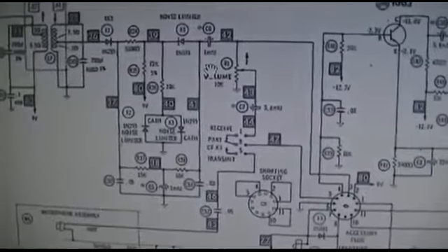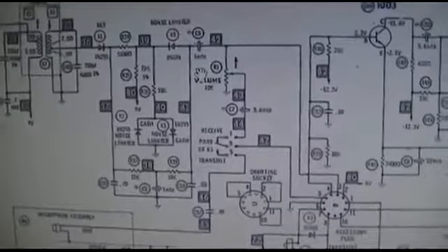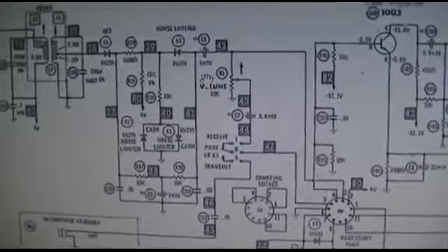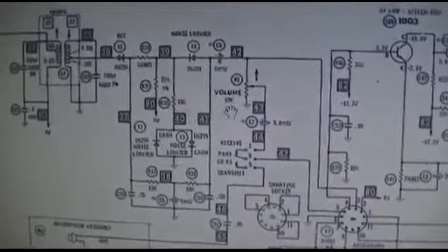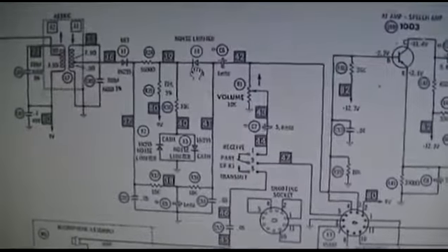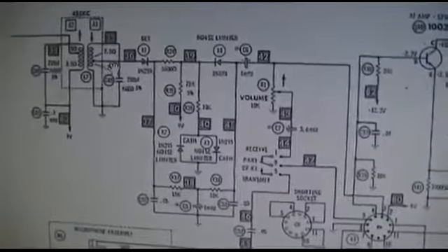We know it needs to be completely recapped. I'm not arguing that. I'm just simply saying let's diagnose it and figure out, you know what would make short work of this? A signal tracer. That's all we need is a signal tracer. You just start right at the output of this IF transformer.